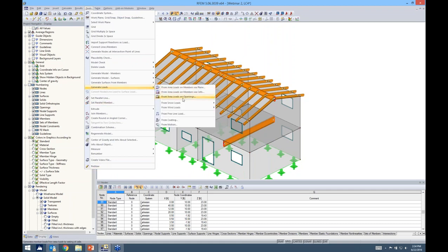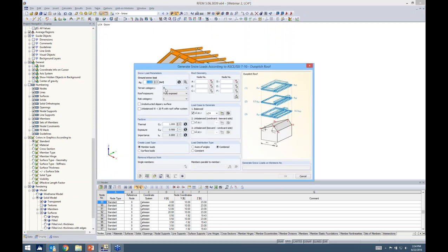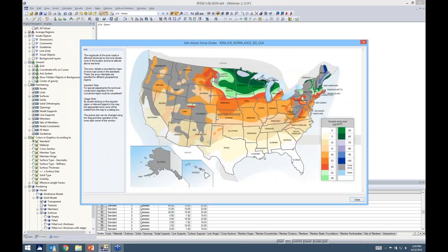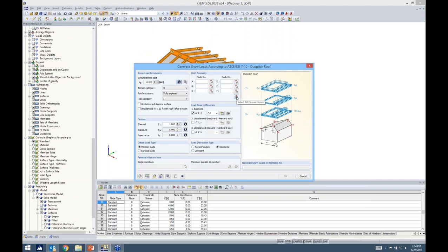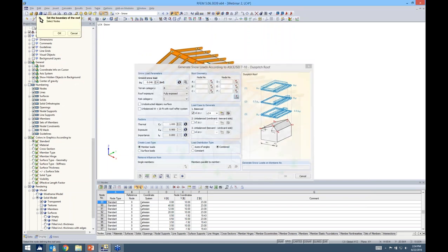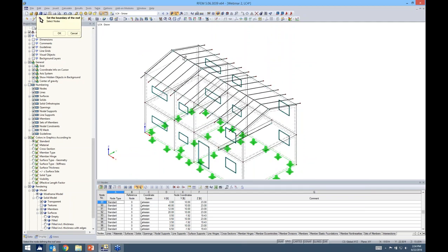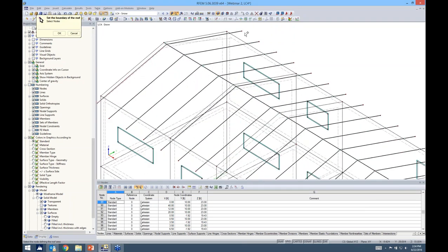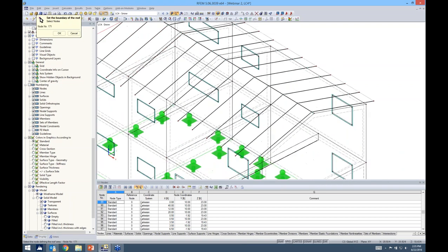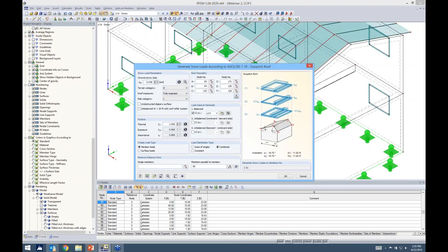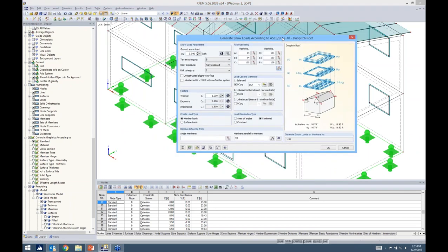If I go ahead and generate my loads again, I think there might have been some issue with the load combination generator in terms of my roof geometry. So for this, I can actually go ahead and select my options again, but this time I'm going to turn it into wireframe to see if that works a little bit better. Maybe I was not selecting a proper node. And okay, much better. Now I can, so that's a good point to make, that if you don't correctly define this